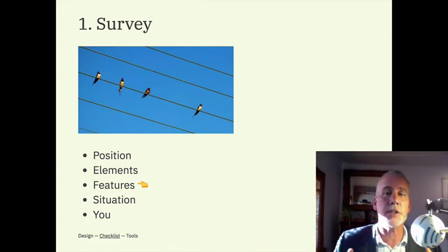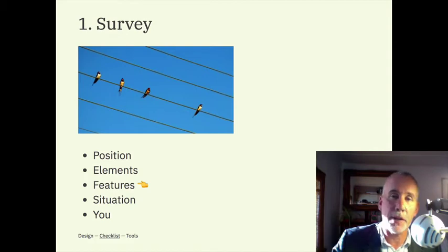And finally, structures, existing structures. A favourite is finding the concrete foundations of an old greenhouse or something. You're not even aware that it's there, but this is the kind of stuff you need to find out. And finally, access, public footpaths, and where the existing gates are. If you need to consider putting in another gate, that's kind of critical as well. And finally, the situation.